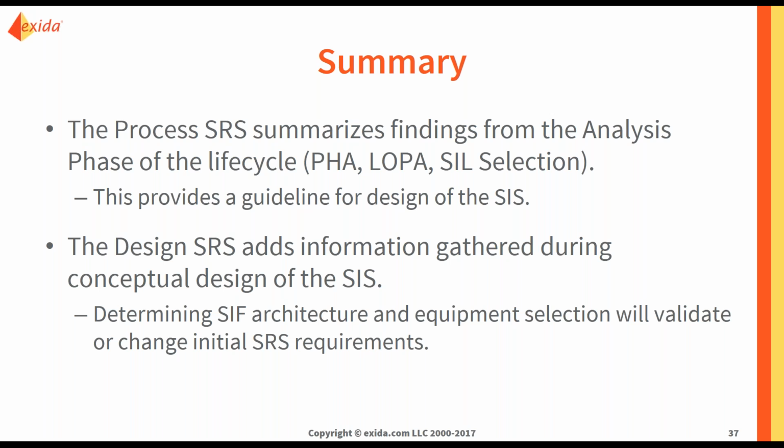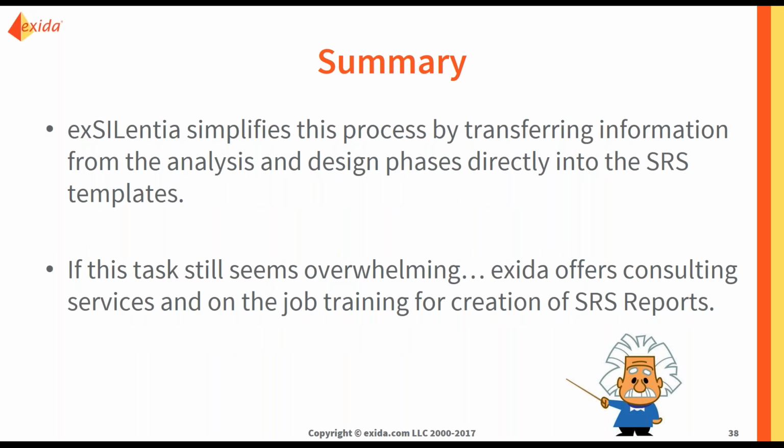And instead of rewriting or having a new revision to what could be a contractual document, you now have a second document that has all of the information combined. So exSILentia strives to simplify this process by transferring information from the analysis and design phases directly into the SRS templates. And like I said, the template also acts as sort of a checklist. You can go through and make sure that you've considered all of the requirements that the standard wants you to consider, to document, and to communicate.